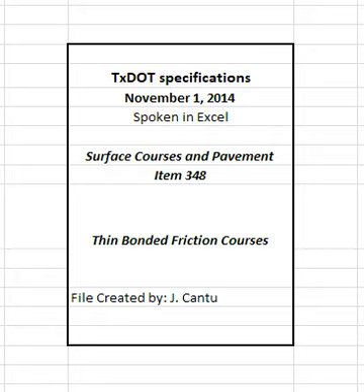Provide the engineer the AR binder blend design with the mix design, JMF1, submittal. Provide the engineer with documentation such as the bill of lading showing the quantity of CRM used in the project unless otherwise directed. 2.5 Membrane. Provide a smooth and homogeneous polymer modified emulsion meeting the requirements of Table 4. Table 4. Polymer modified emulsion requirements. See table in specifications.